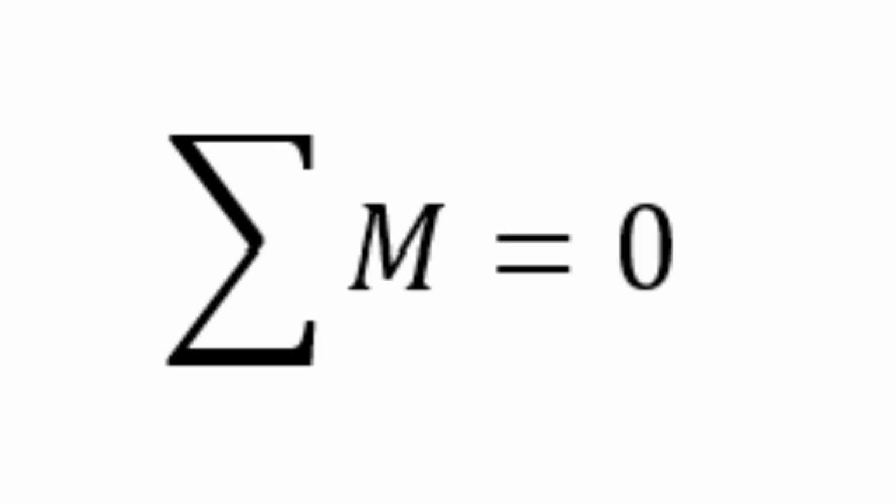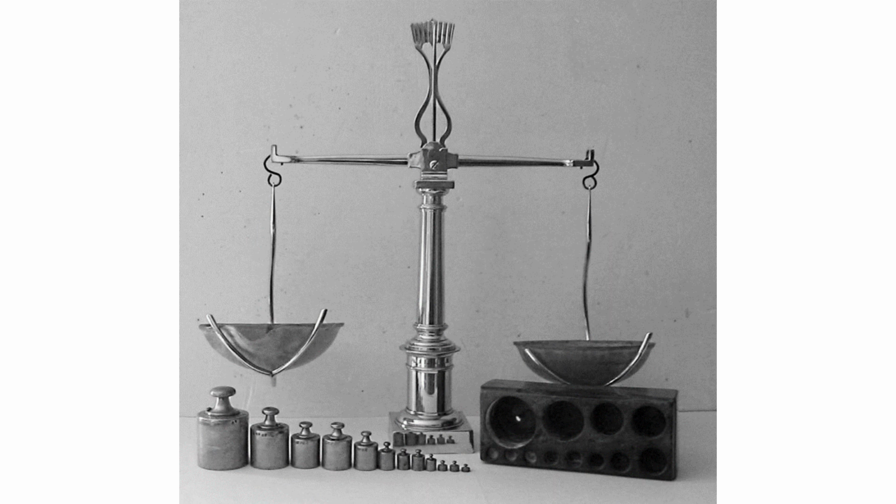Equilibrium of turning moments. When a structure or machine component is in equilibrium, the moments, as well as forces, must be in a state of balance, otherwise the unbalanced resultant moment would cause rotation of the body as we just seen. Thus for a body to be in rotational equilibrium, the resultant moment about any point must be equal to zero, meaning there must be no resultant turning effect. Mathematically this can be stated as: